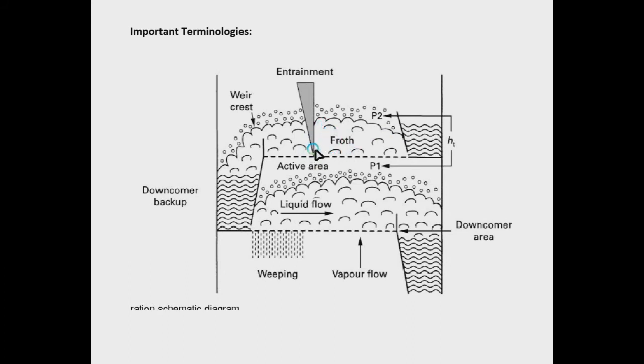So for example, in the case of bubble cap, the vapor bubbles through that liquid, and the weir is actually only a slight extension of length at each plate that allows a certain amount of liquid to be accumulated at that space. This is called the active area of the plate, because the downcomers are not active and there is only vapor upflow or liquid downflow happening there. So this is the active area of the tray.